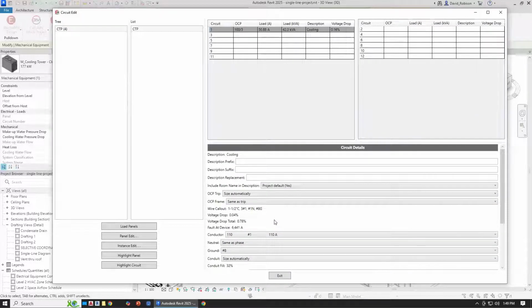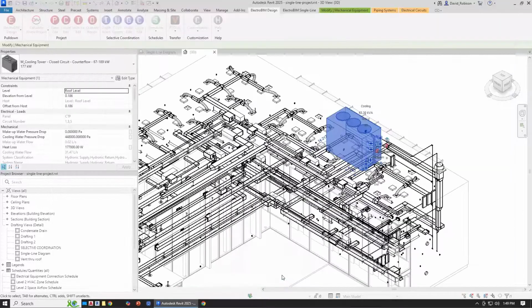So this is all for when we're sizing the ground automatically. If that automatic sizing is upsizing more than you want, you can always go into the ground and change it to what it should be specifically. That is what we do for sizing grounds. That's the equipment and service ground, NEC 250.122 and 250.102.